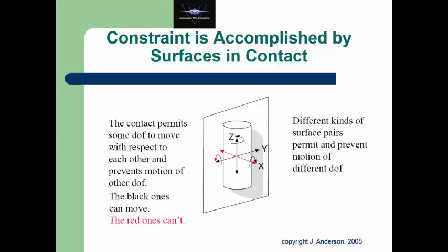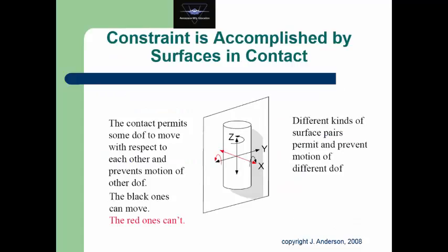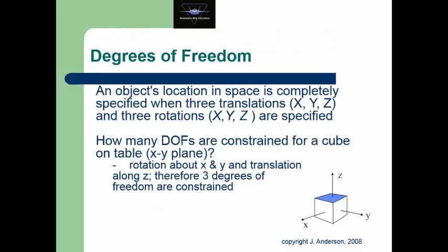It can move linearly along the x-axis, and it can also rotate around the z-axis, rotate around the x-axis, or rotate around the y-axis, or combinations of those basic movements. So those six motions that we just talked about are referred to as 6 degrees of freedom.